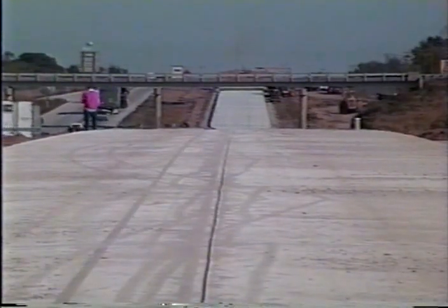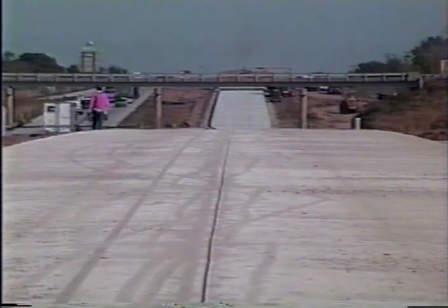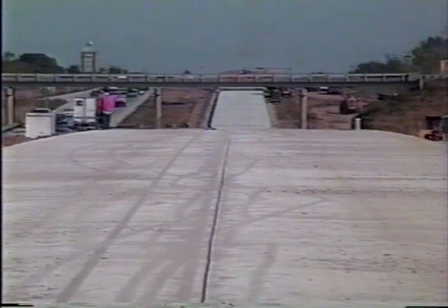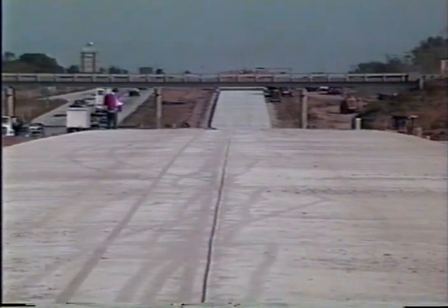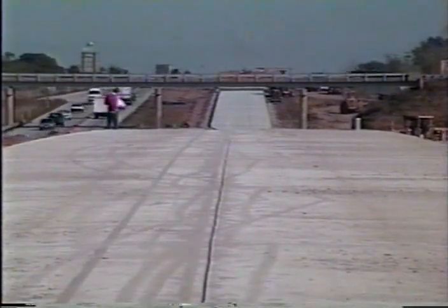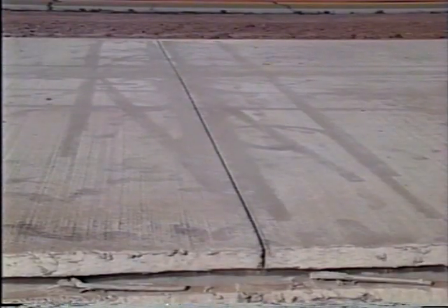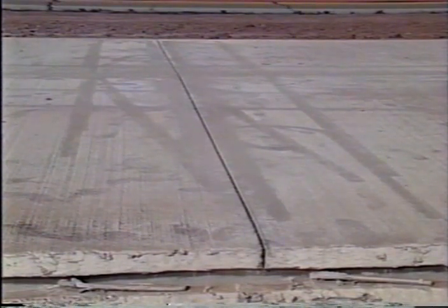Unbonded concrete overlays on jointed, plain concrete pavements require shorter joint spacing than other concrete pavements do. The thermal gradient, friction with the separation layer, and very stiff support provided by the underlying slabs all help create greater curling stresses in the overlays. Either shorter joint spacing should be used or reinforcement should be provided to control any cracks that may develop.